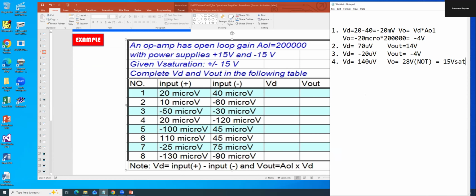So I have a question. Is this like how when I put something into the outlet, maybe it's too strong, and instead of producing 28 volts, it produces 15 because it's safe? Is that how the op amp works? Right. The op amp output cannot be higher than the power supply, and in this case the power supply is plus and minus 15 volts.